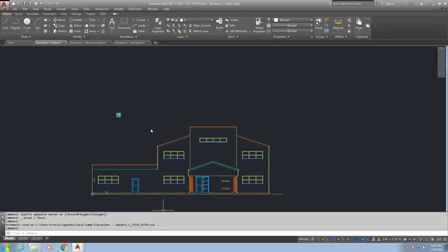So the end point, the text, the M text, the block, the arrowhead, that's all customizable. The point of a leader object, just like on these other annotation objects, is to annotate one or more objects in cases where placing text directly next to the object would not be feasible. Maybe there's not enough room. Maybe there are a bunch of things jammed together and putting text in there really close up just wouldn't work. That's where leaders come in handy, and we'll take a look and see what these look like.